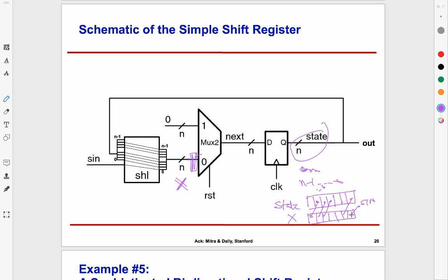So a barrel shifter is a specialized module which does that. Most computers have it because programming languages like to have this option, shift by less than n, where n could be arbitrary. So shifters are a valuable part, but they are pretty easy to implement.